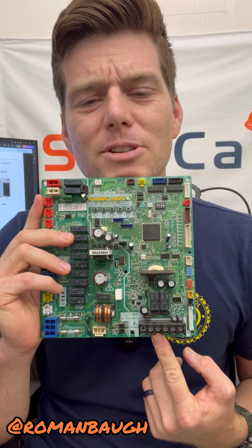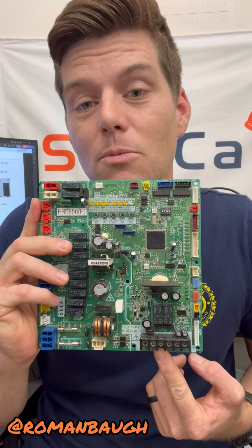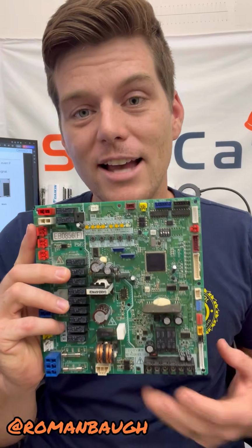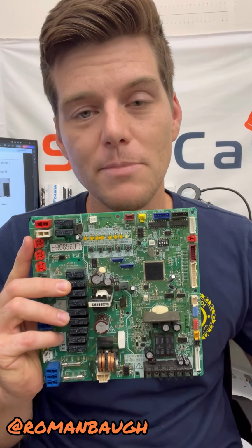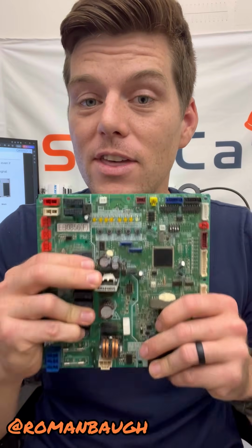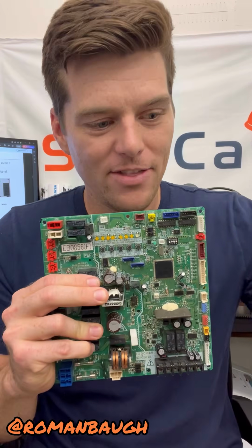The outdoor unit says, hey, there's a centralized controller here. I don't need to generate this anymore. And so it stops. And now all the outdoor units go into restart standby. They recognize that there's a centralized controller and they all stop generating the 16.5 volts DC. Why is that important to notate, that these lose that power and the ITM is generating it?